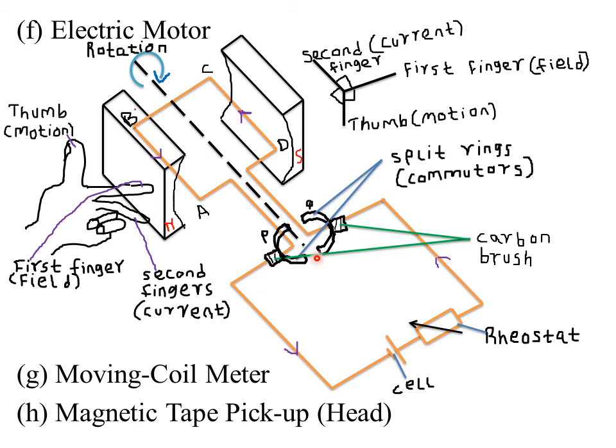In this position, when AB is up and CD is down, the brushes touch the space between the two halves of the split rings, cutting off current flowing in the coil. Consequently, no force acts on the sides AB and CD. But because the coil is rotating, its momentum carries it past this position, and the two split rings exchange the brushes. Remember, in the next rotation, this side will be on Q and this other side will be attached on P. That is, the brushes exchange the sides of the conductor.